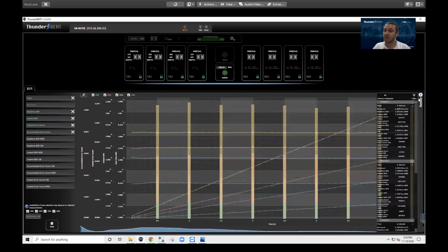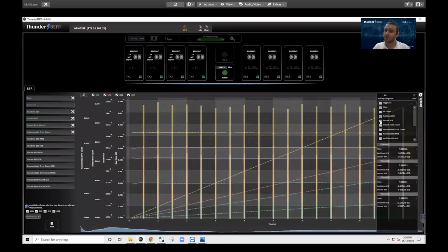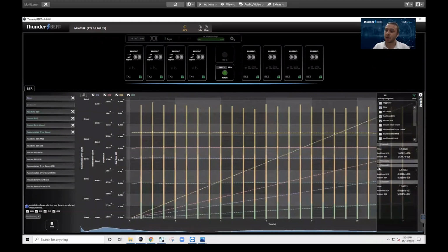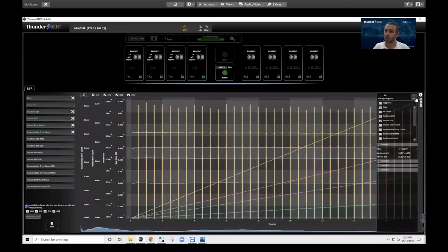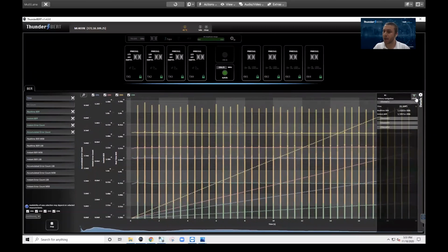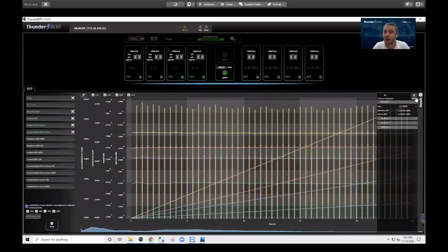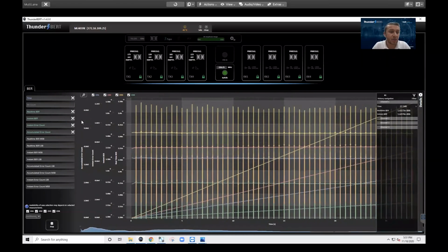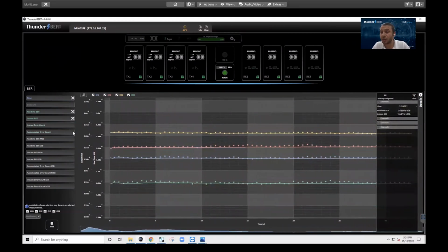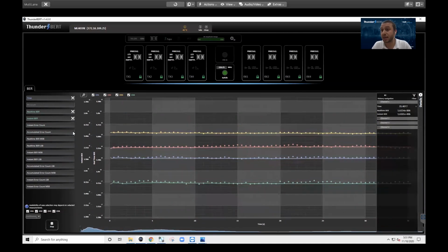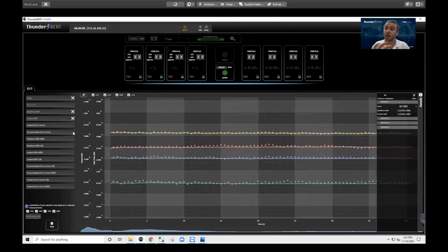I'm going to go into the details tab, and this time I'm only going to show time, real-time, and instant BER. And let's say I show just channel 1 to focus on one channel, so that I can simplify my real-time readout. I turn off the filter tab, and you can see channels 2 to 4 are minimized, but we still have all measurements coming in. I can stop measurements on the graph, but that will not change the fact that the measurements are still being tracked in the details tab.